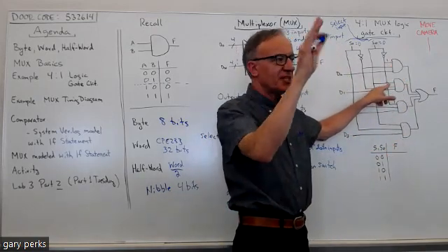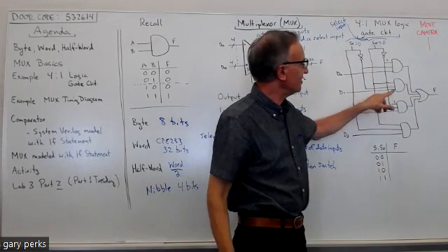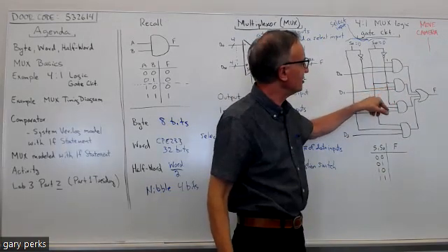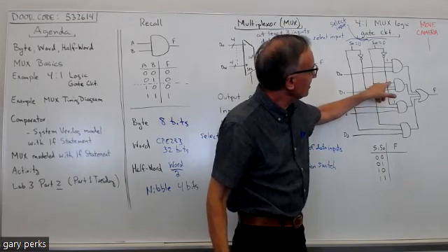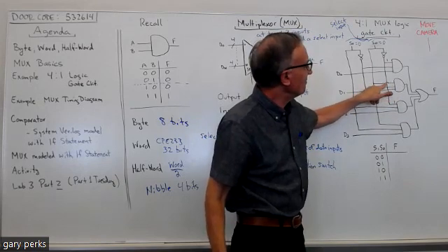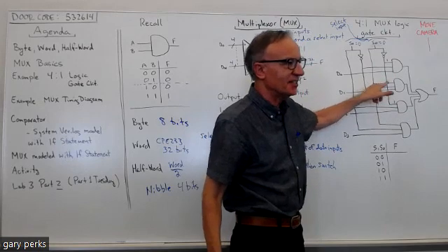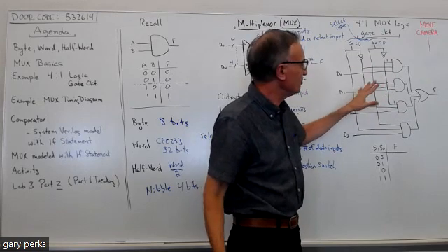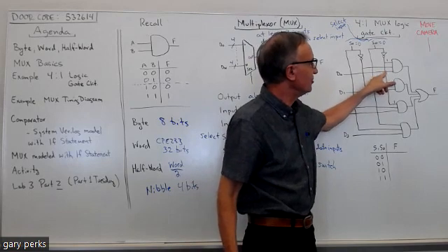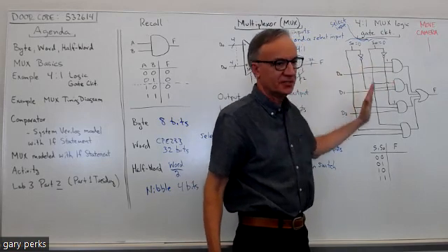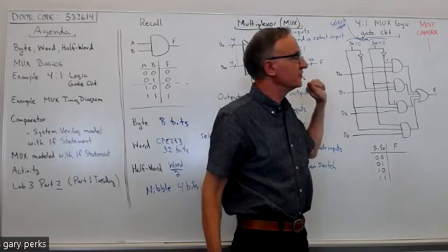In old diagrams, so this is back in the day, I don't think they do this much anymore. But in old diagrams, you'll see a little hump. That's just to emphasize that there's no connection at that intersection. But in most diagrams nowadays, they don't do the little hump. It's just understood that if there's no dot, there's no connection where they cross.